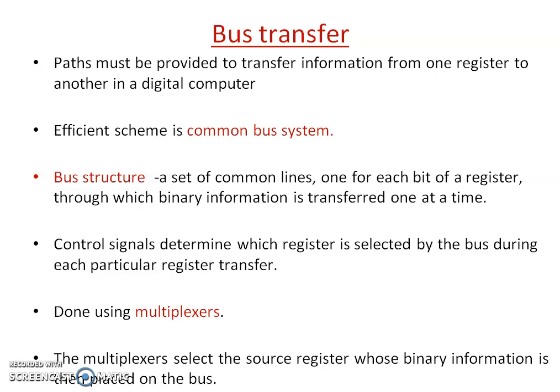Altogether, that example specifies that more than one source register will be there. In one time variable T1, content of A will be transferred to C, and in another time variable T5, content of B will be transferred to C. So the source registers were A and B, and the target register was C.